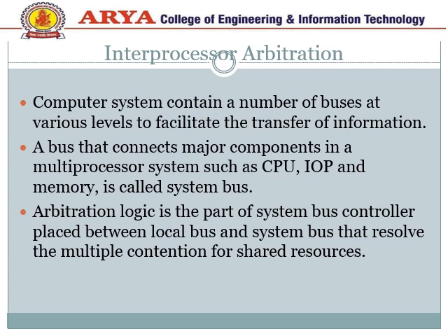Interprocessor arbitration. A computer system contains a number of buses at various levels to facilitate the transfer of information. A bus that connects major components in a multiprocessor system, such as CPU, IOP and memory, is called the system bus. Arbitration logic is the part of the system bus controller placed between the local bus and system bus that resolves the multiple contention for shared resources.